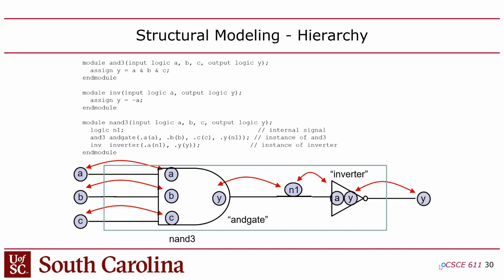And then likewise, A is connected to N1, the A input, and this Y. So this wire in the middle is actually renamed twice because it's called N1 here, it's called Y inside the AND gate, and it's called A inside the inverter. But when you synthesize this to hardware, it's all just one wire, right? There's a feature in Altera called SignalTap.